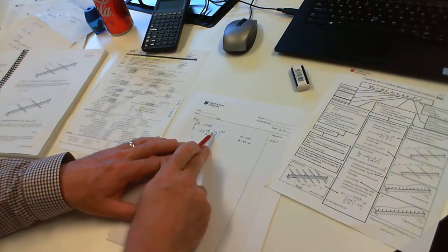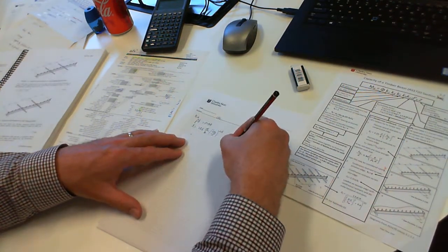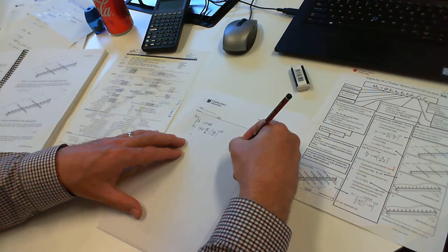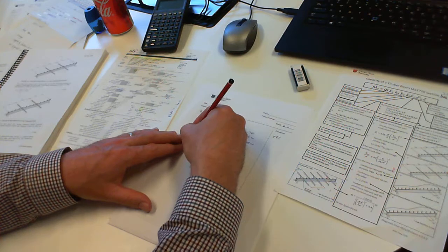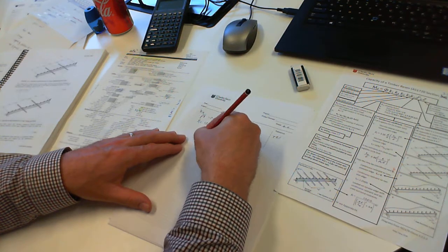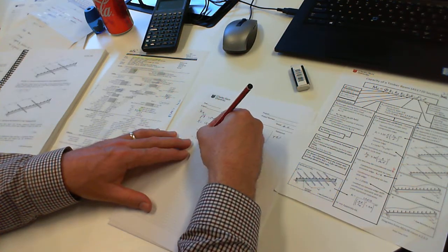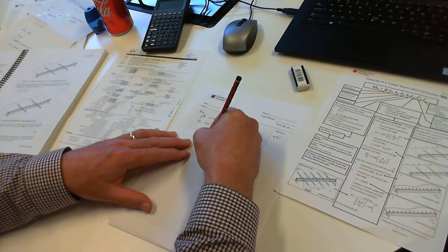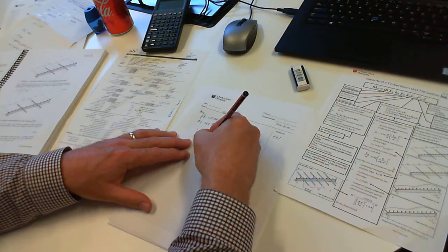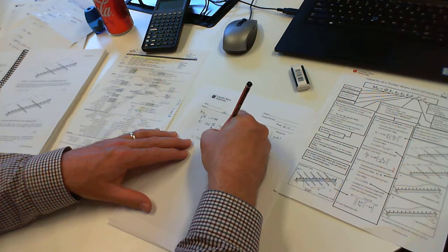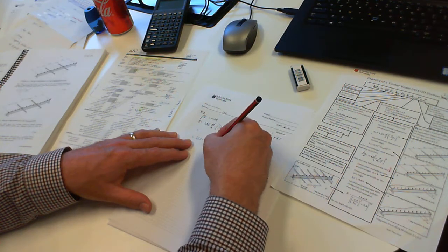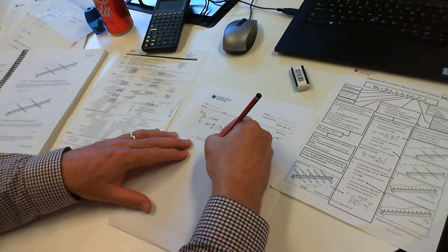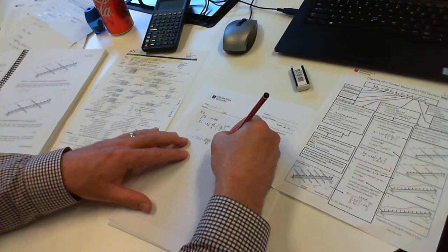And our lay equals 900 millimeters. So we've got all the different bits. Let's put it together now. So 1.25 times d, which is 240, over b, which is 45, times lay, which is 900, over d, which is 240, all to the power of 0.5.